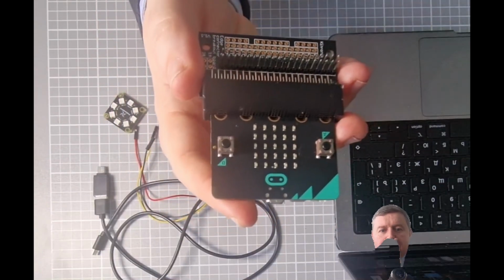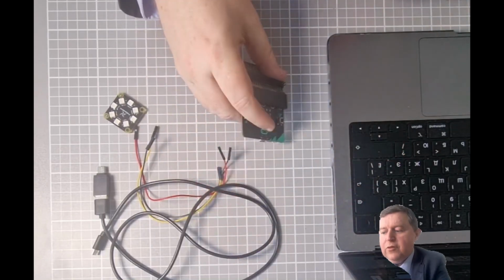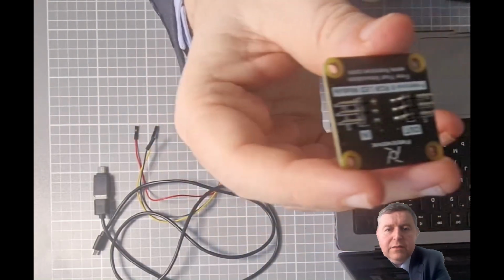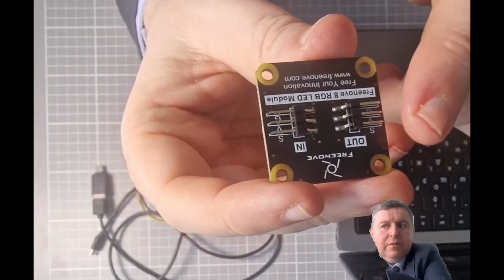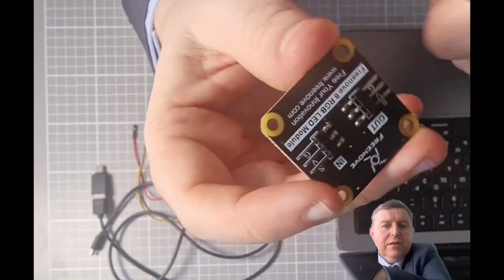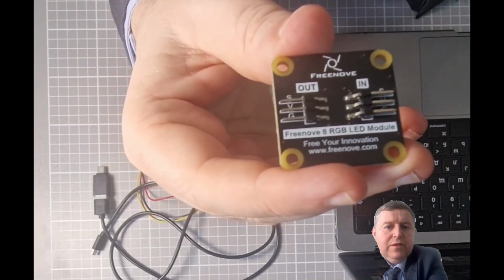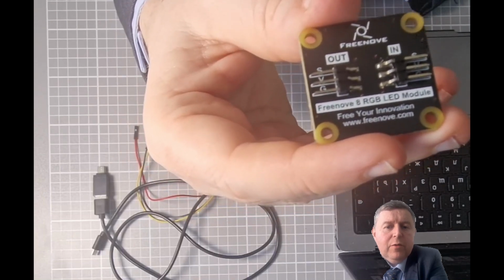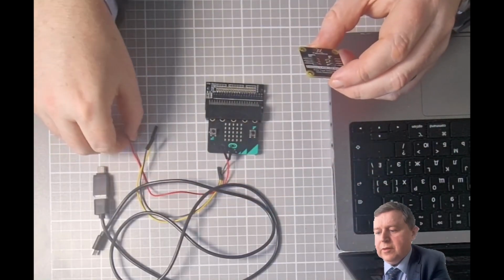There's the buttons. Okay, next thing we want to do is connect our NeoPixel to it. I'll just show you on the back here. There are some pins on the back of it. We're looking at the in pins this time. There's one for S, V, and G. Actually, if I turn it around, maybe you'll see it better. So there's S, V, and G there. The signal is the S one, voltage is for power, and G is for ground.